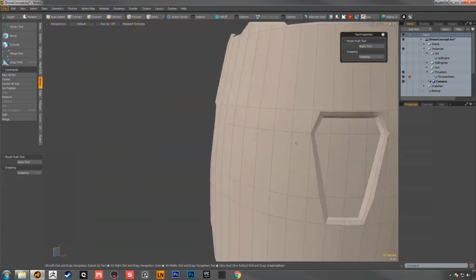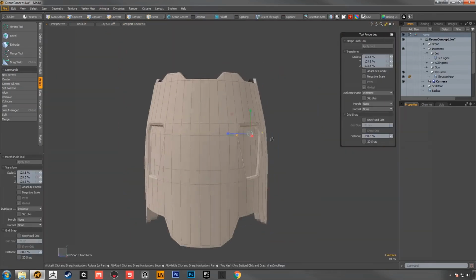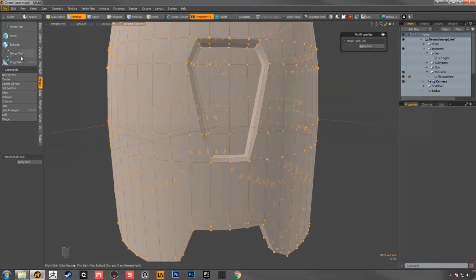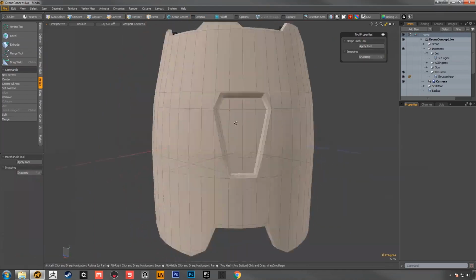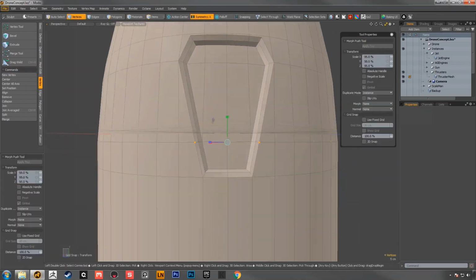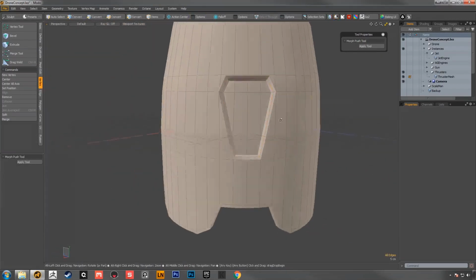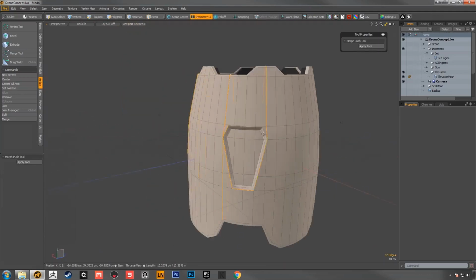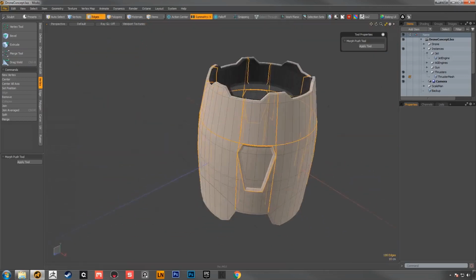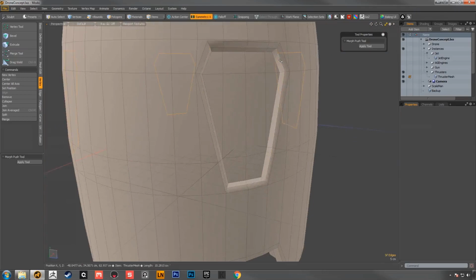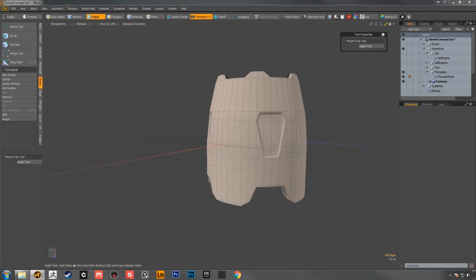So what I'm doing now is I'm going into my boosters and I'm just adding those single bevels that I will be doing all over the bodywork for the whole vehicle, because all of these white elements will not be baked into the components at all. They'll just be using tiling textures with no individual normal maps. So I just want to figure out how big the actual bevel needs to be, then soften those, run my force normal script, and basically that's how I leave it.